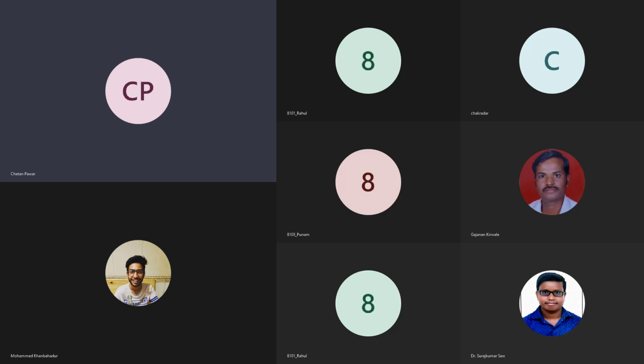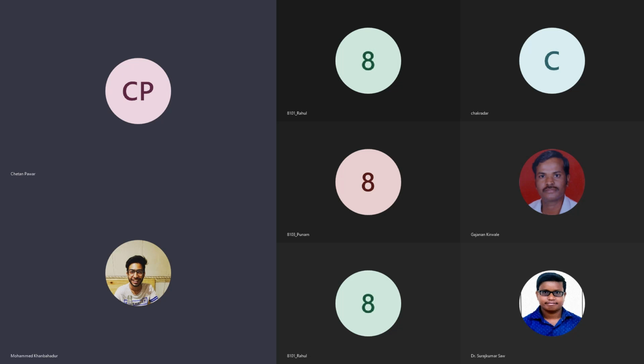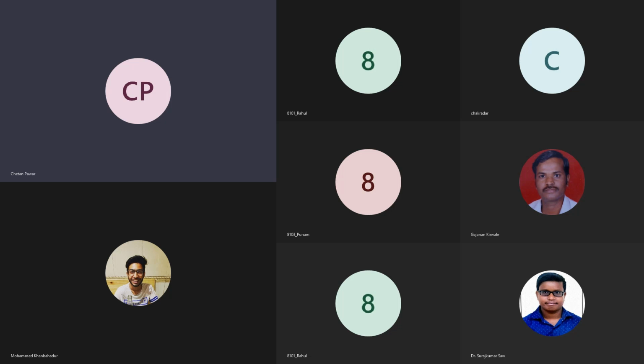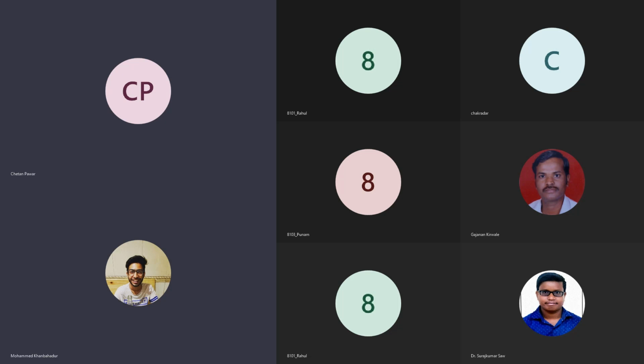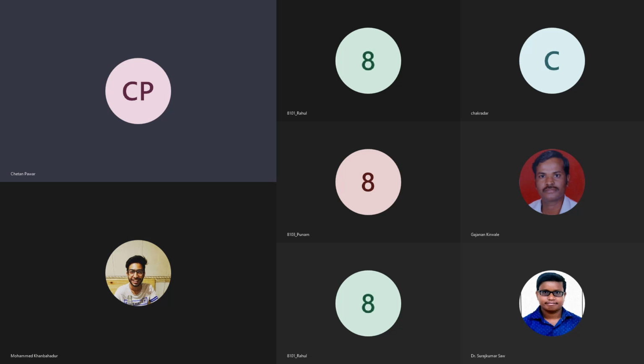So you just made one mistake. Connect that source between the gate and source. Now the upper terminal is the source. So the DC voltage you have connected should be between gate and source, the upper one. On the left-hand side there is a VGS. Yes, VGS. So source is your upper terminal, not the bottom one. So that DC voltage should be between those two terminals. Right, sir. That is basic only.